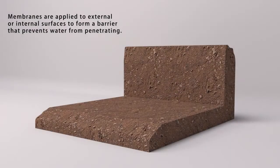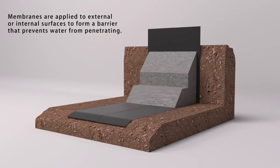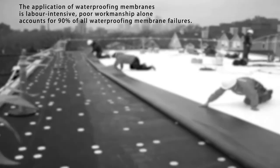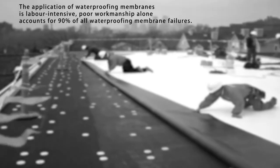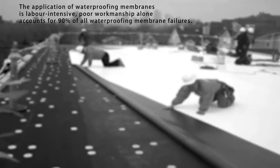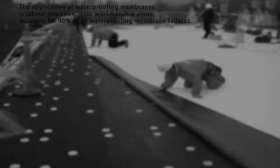In concrete waterproofing, membranes are applied to external or internal surfaces to form a barrier that prevents water from penetrating. The application of waterproofing membranes is labour-intensive, requires skilled applicators, and is therefore often destined to fail. Poor workmanship alone accounts for 90% of all waterproofing membrane failures.